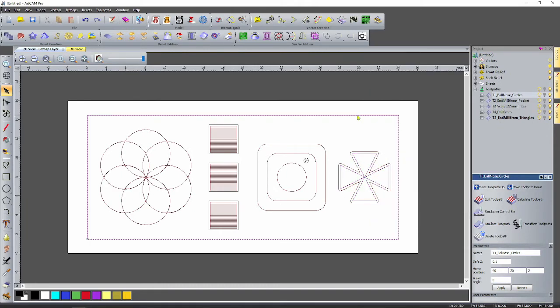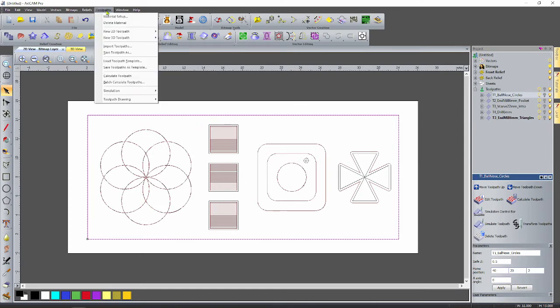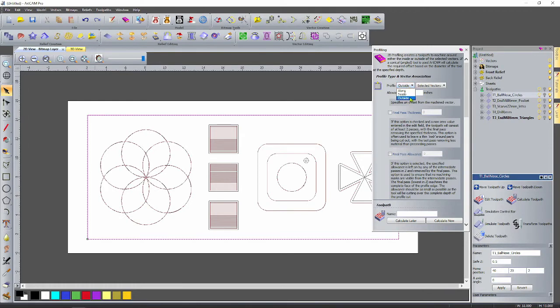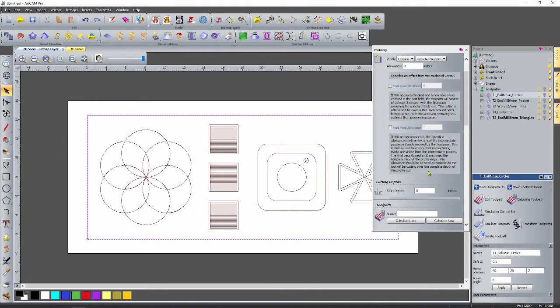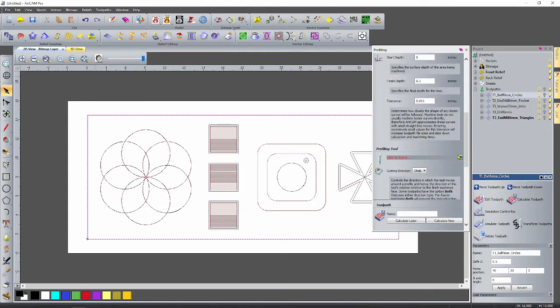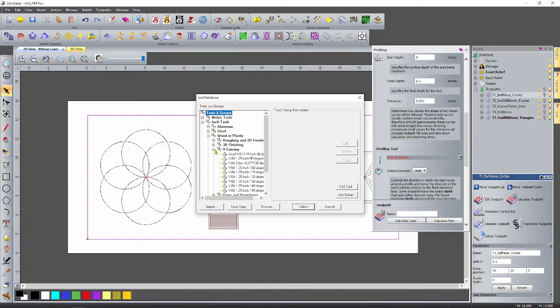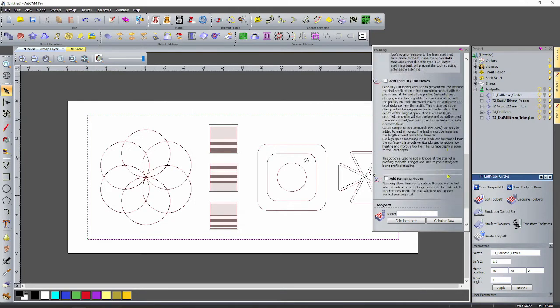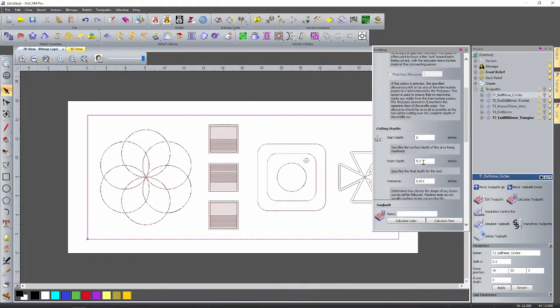Oh, we cut out. Select it. Profile. For this one, we use the outside. And since I'm gonna use an end mill, which is a straight end mill 6, it's gonna give us the exact dimension that we're gonna have here. So select it and finish depth. Start depth 0, finish depth.